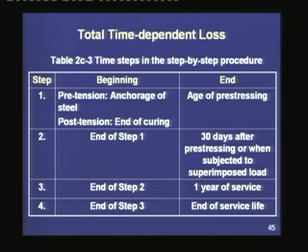This period is, say, roughly around 30 days or slightly more, and it is a small time step because there is a large variation of the pre-stressing force due to creep and shrinkage in the first month after the pre-stressing of the concrete member.